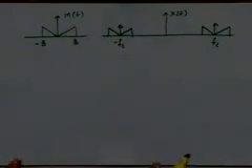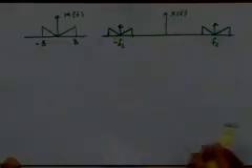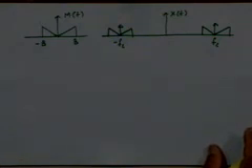So the only way the spectrum of the AM signal differs from the spectrum of the AM signal with suppressed carrier is that this carrier component is not present there. I hope that also answers the question as to why we call the earlier kind of signal DSB-SC, right? It is basically this difference.